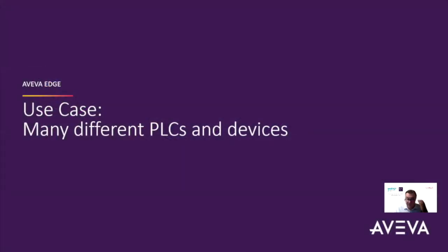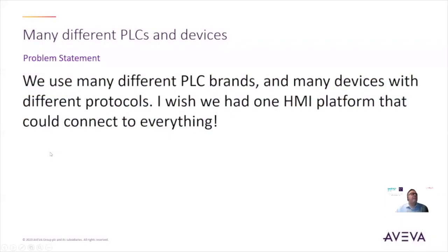So the first use case, first here of 7 that I have to show you today, many different PLCs and devices. So something that we often hear is we have many different PLC brands and different devices with different protocols. I just wish we had one HMI platform that could connect to everything. And this is something that we hear, especially going up against our competition, where the number of drivers that they have is often either small or non-existent, and you have to add external technologies or external modules, things like OPC, or add on things to get to additional protocols.